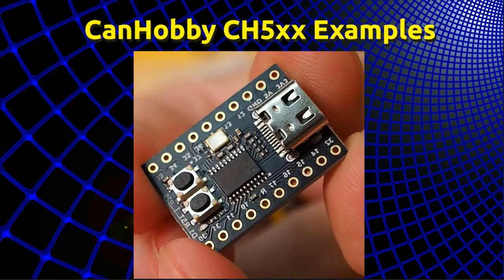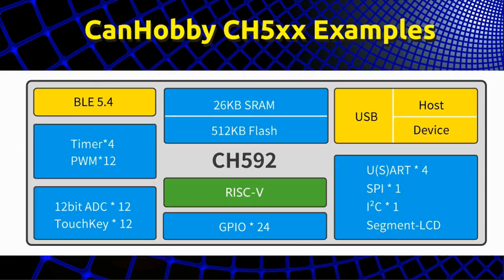Although I developed this project on a CH582 board, I specified the 592 because there is no repo for the 582 board, only the 583, and the CH583 repo does not include samples for SPI0. The 83 has two SPI interfaces, but the 82 only has one.